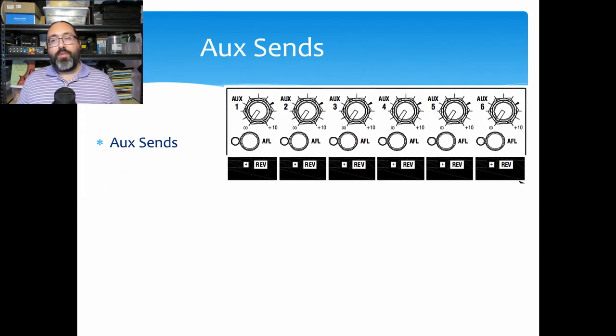So to the left of the console, we have our aux sends. We have 6 auxes for this console. As I said, aux 1 and 2 are preset. Aux 3 and 4, we get to choose whether it's pre or post fade per channel. And then 5 and 6, we also get to set as groups. Now, on this console, the suggestion that I have with setting the auxes is just like you have to bring up that main fader left and right, you also have to bring up this knob, this potentiometer, to some level to get that output onto the rest of your system.